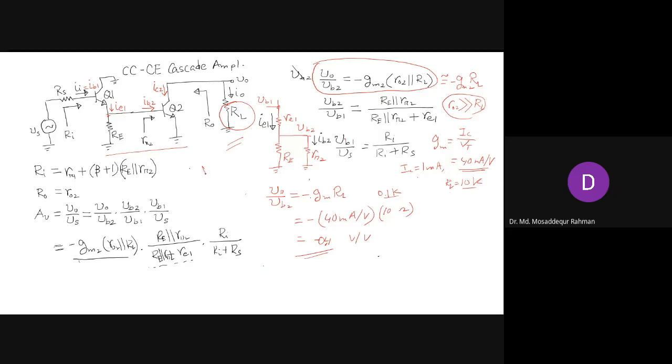The speaker, usually, is a coil, and a coil has very low resistance, usually in the range of a few ohms. Like I said, let's say the load is 10 ohm, really around this range. So in that case, you can barely have any gain. The gain is heavily affected by the load resistance. So there is a problem: if load resistance is high, then you get high gain, but you don't have any control over that. So how can you overcome this problem?